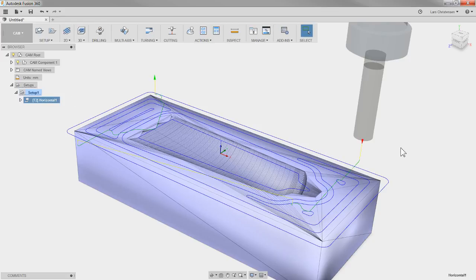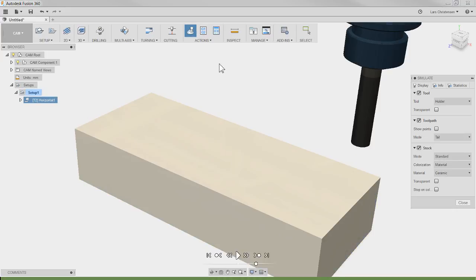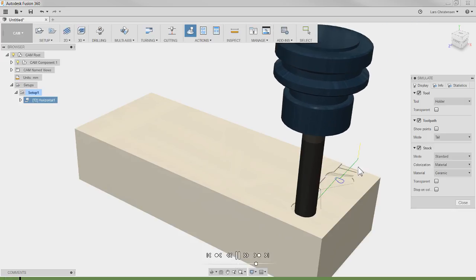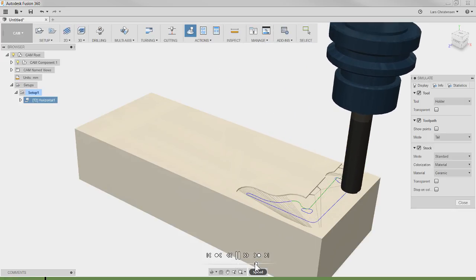I always say that whenever we are doing a 3D toolpath, the best, I don't know if it's the best, I shouldn't say the best. My rule of thumb, because what the heck do I know? My rule of thumb is whenever you're doing a 3D toolpath, select your tool, hit OK, see what the software gives you. So you will see we get something here that could resemble a facing operation. Now, it's not necessarily perfect per se, but it will definitely face off most of the part here.